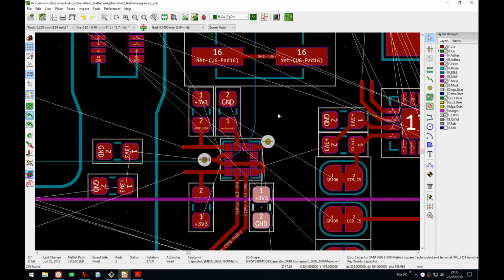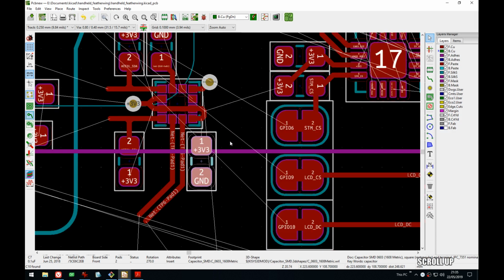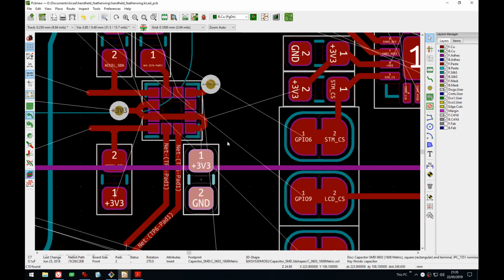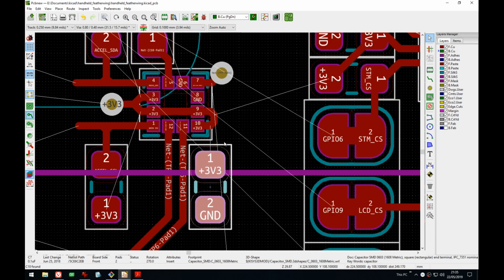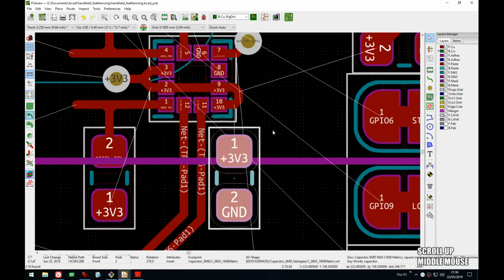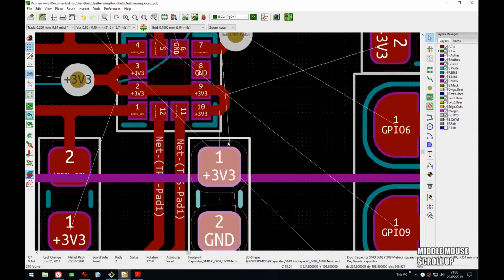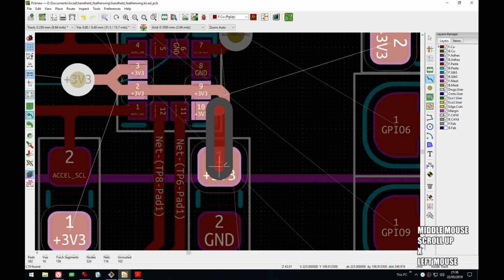And the good routing obviously is even more important, because decoupling should be as close to the chip as possible. So this is always a fight between being, I don't know, electrically correct and aesthetically correct. Let's call it that. I was starting to create vias here just so I can have that capacitor there. Yeah, it's not worth it.